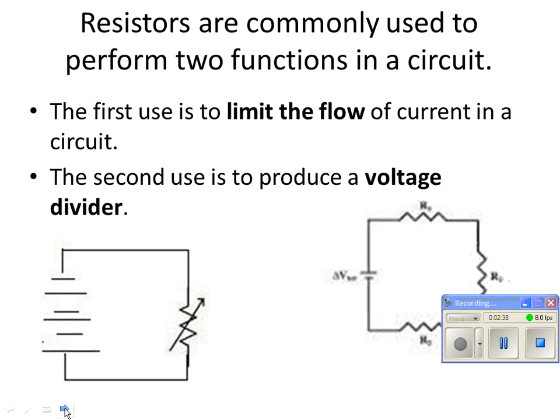Now probably we just blew up the resistor because it won't take 12 amps, probably, because it's wattage rated. 12 amps times, what's power? P equals E times I. 12 times, what's the current? 12 times 12, 144, right? Most resistors are rated at 1 or a half or 5 watts or 25 watts. So if we're flowing 144 watts, we've probably just burned up the resistor, right?